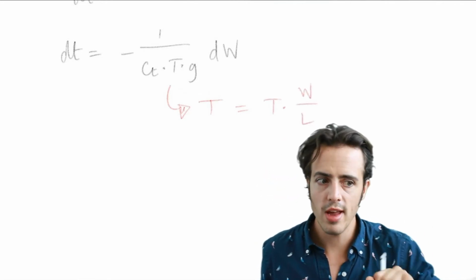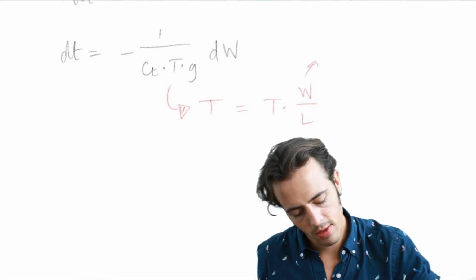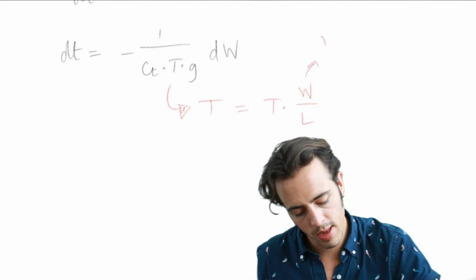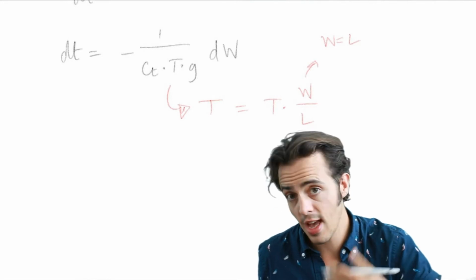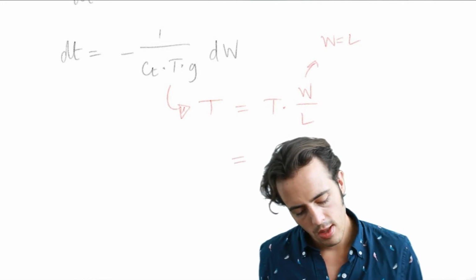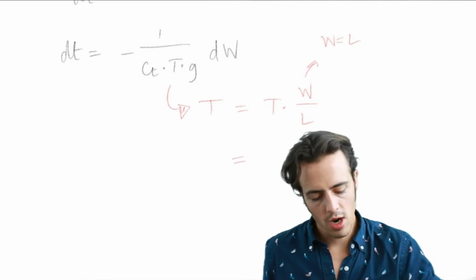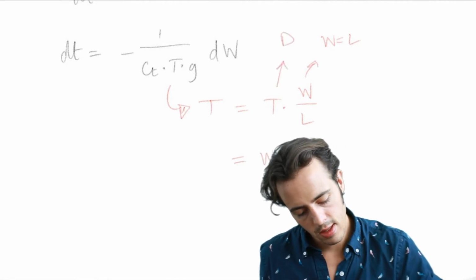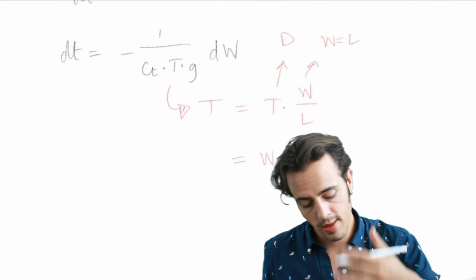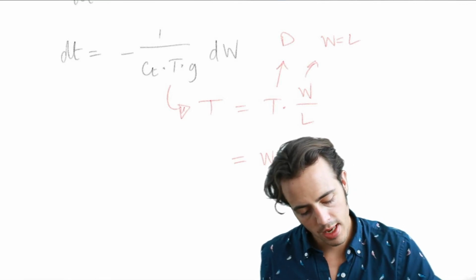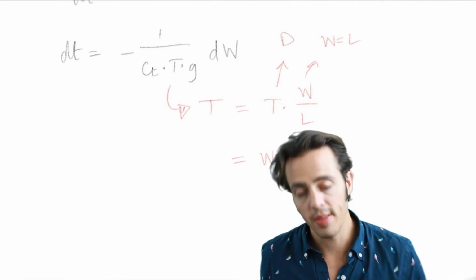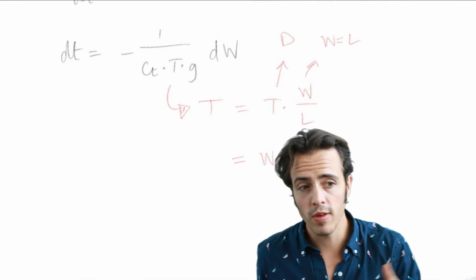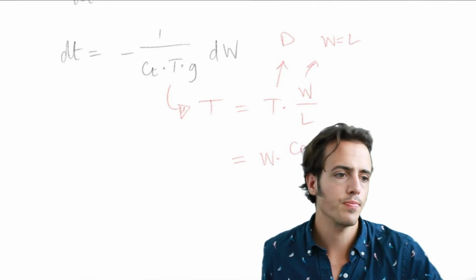Now those two are actually the same quantity, because remember that weight is equal to lift, so this is therefore equal to 1. So then we could say that for our problem, remembering that thrust is equal to drag, the thrust is equal to the weight multiplied by the drag divided by the lift, or 1 over the lift to drag ratio.